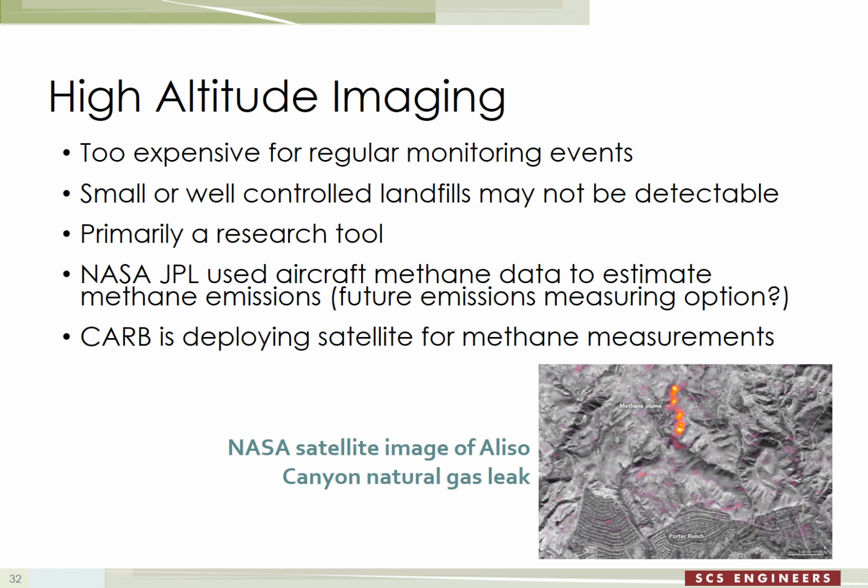But again, the NASA study was able to see methane plumes from a lot of landfills, and they actually were able to convert data into actual emission estimates using their own algorithms. So they not only took it from the imaging and concentration hotspot measuring, but they were actually able to turn it into emission rate or flux measurements.